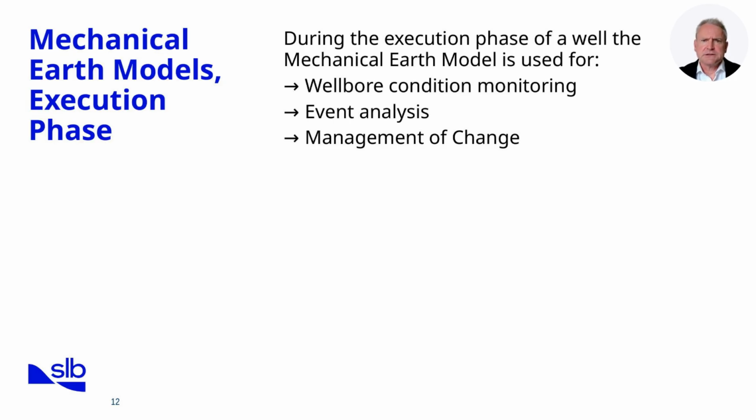Management of change is the third key area. Conditions often deviate from plan, and the MEM helps justify operational changes. For instance, if pore pressure turns out higher than predicted, the model supports raising mud weight or adjusting casing depth with a clear geomechanical rationale. With torque and drag, hydraulics, and MEMs covered, we can now review the module objectives.